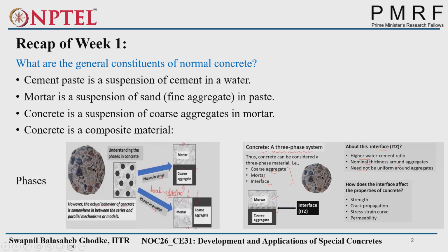But in the high strength concrete, the mortar is very strong, and similarly, the ITZ is also strong as compared to normal concrete. So in that case, what happens? The crack will occur through the aggregate. The aggregate will be broken down. So if we have two samples after the crushing compression strength test, one has the crack happening surrounding the aggregate, and the other has the aggregate broken down. So we can easily say that wherever the aggregate is broken down, that is the high strength concrete, with visual inspection itself.